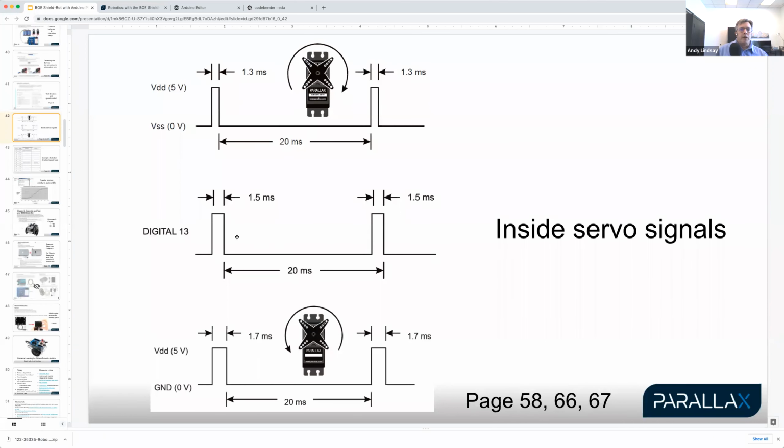And our servos were typically a little bit out of calibration coming out of the box. And so what we did was we used that screwdriver to adjust the potentiometer to set it so that this signal right here is exactly what would make the servo stay still.